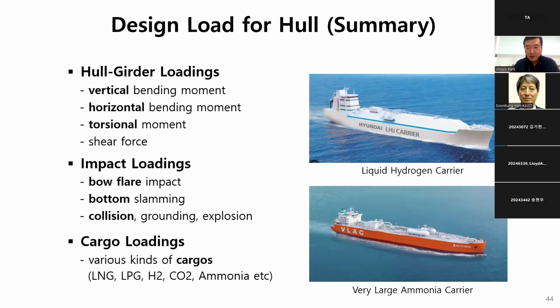Yeah, it's the last slide summarizing design loads for our structure, which are horizontal loadings, vertical, horizontal, torsional moments and shear force, impact loadings, bow flare, bottom slamming, collision, grounding, explosion. Sometimes cargo loadings, various kinds of cargo loadings are included in the initial design stage.